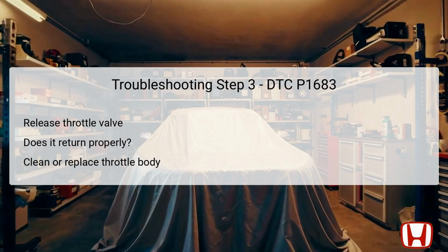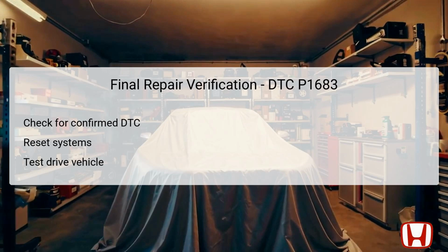However, if the valve does not return properly, it's a clear indication that the spring mechanism or throttle body itself is at fault, necessitating replacement. Therefore, the outcome of this check directly informs the next steps in resolving the DTC and ensuring the vehicle operates safely and efficiently. After performing necessary repairs, it is essential to verify the effectiveness of these actions against DTC P1683.